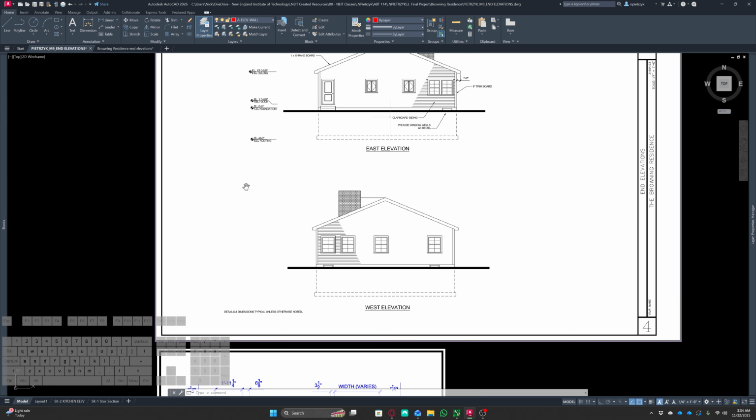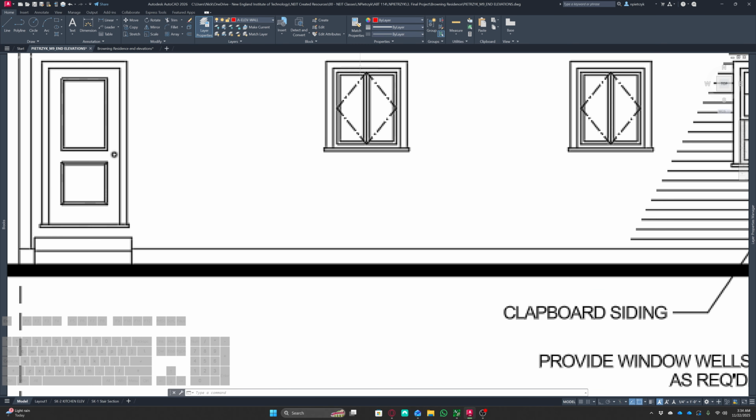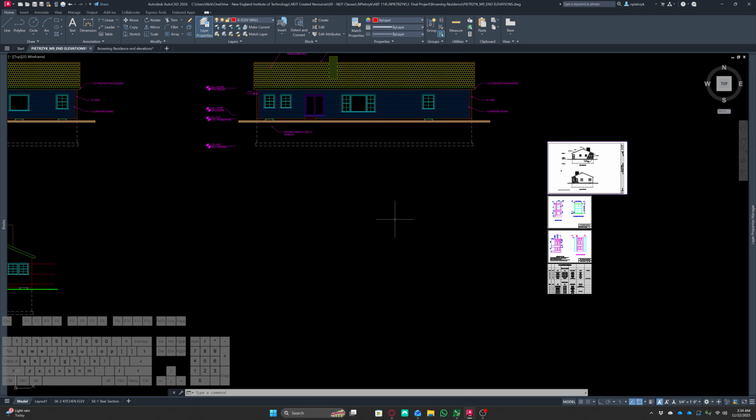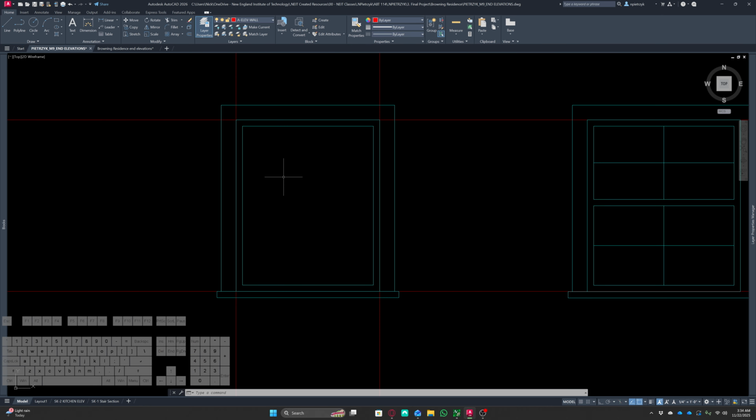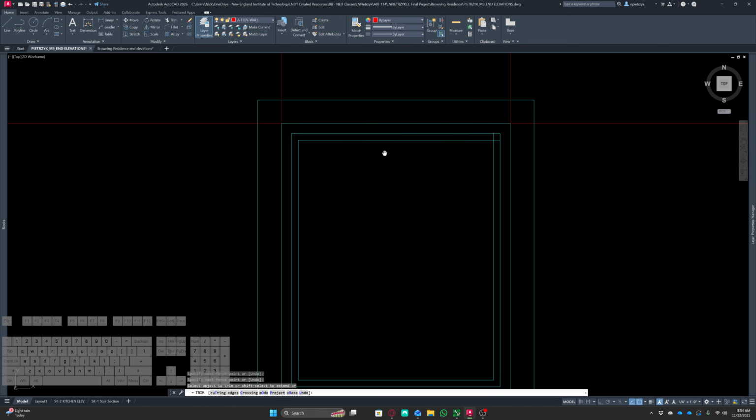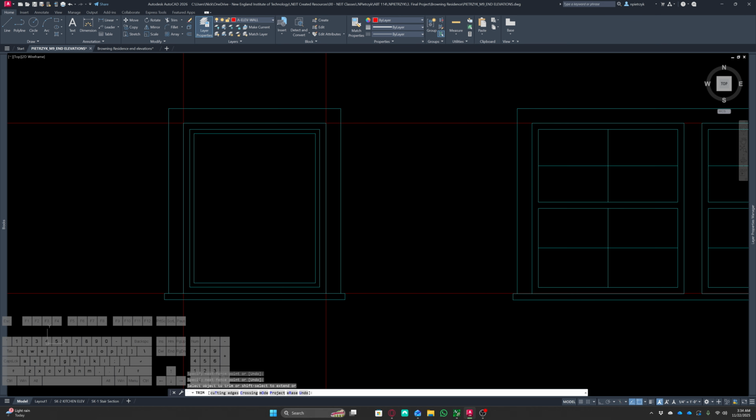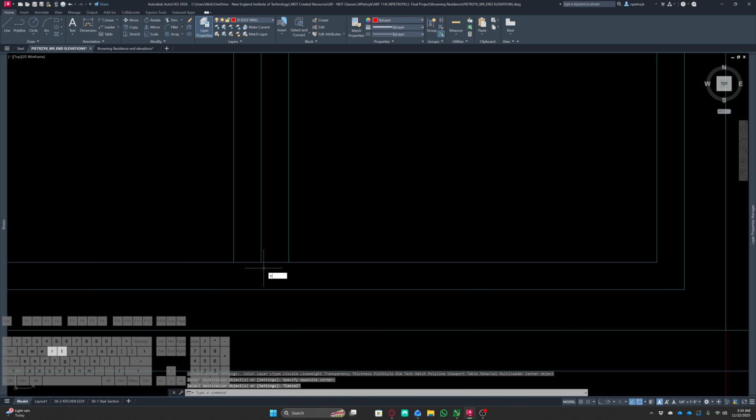But there is a thing that we actually need to do with it, and that is draw another panel on the inside and with that line type. So how do we do that? What I'm going to do is offset by an additional 1 inch personally. 1 inch feels good to me, but if there's not a design for it, just estimate where dimensions are not given. I'm going to draw a line down the center and offset 1 inch onto the left and to the right of that. Do match properties in here.